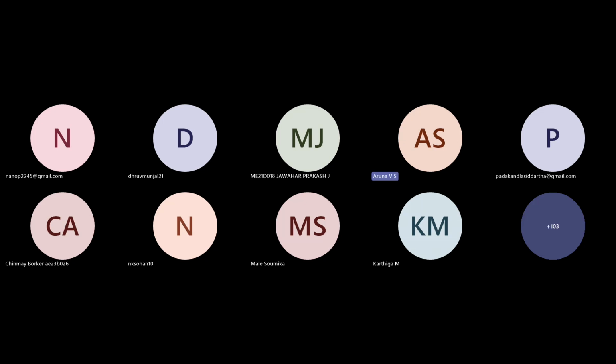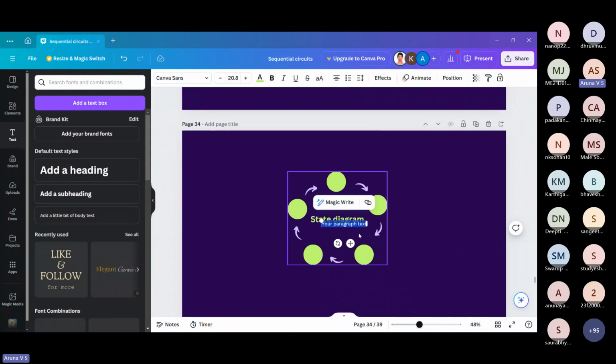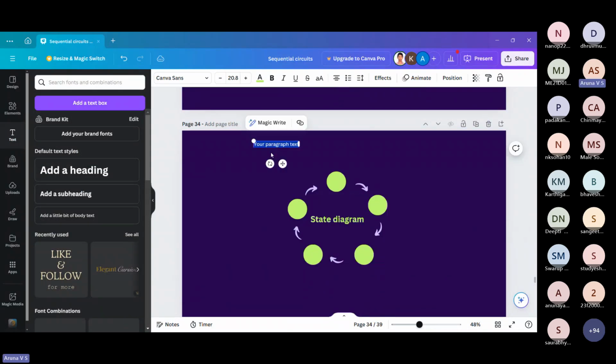Yeah, so now we can just do a random counter. I think the attendance link has been put up in the Q&A session. So we'll do 0, 2, 3, 5, and 8, some random numbers, and check what happens. Since 8 is here, that means we are moving into 4 bits, so we'll be requiring a 4 variable K-map.